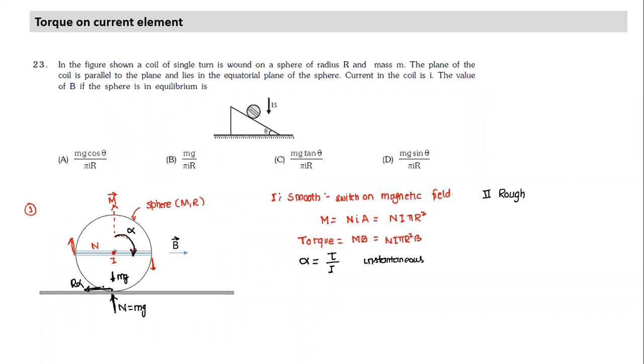So if it is trying to develop acceleration in this direction, the surface will oppose this tendency for slipping. No slipping has started yet. It will oppose the tendency of slipping by applying a friction force in the opposite direction. So the moment the surface is rough, the friction force will start acting. And if the surface is rough enough, the point P will have zero acceleration.